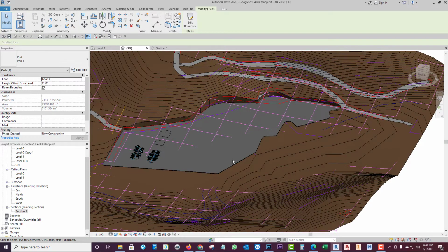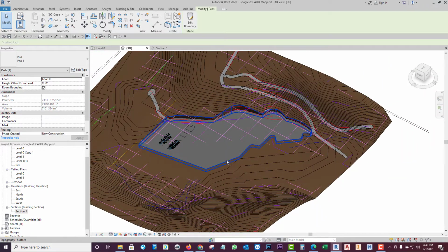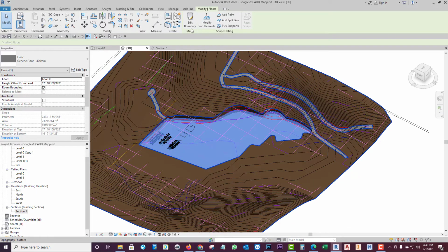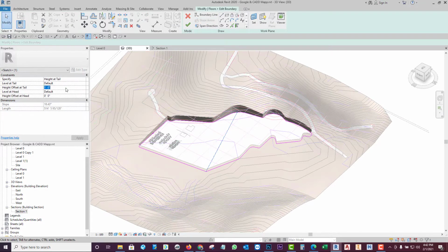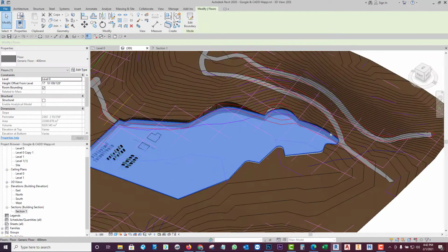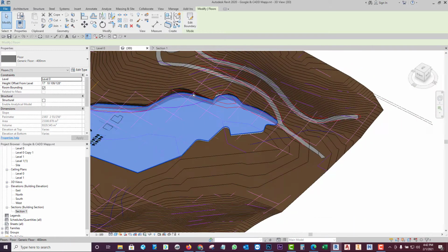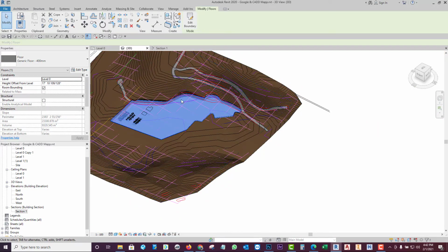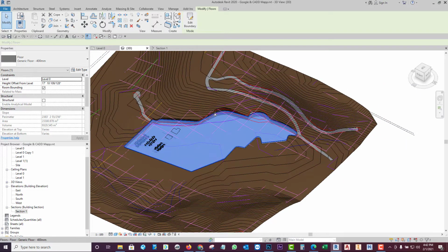So obviously the concrete is going to try to minimize the drop, so I'm going to put a slope on this slab from here to that edge. So I touch the slab, edit, and I put the slope, and I say from this corner to that corner. The height of the tail I'm not going to change, and the head I'm going to put 9 feet, apply. Probably is good enough. Obviously here is the more critical part, but right here is flush, so I'm going to leave it like that because we are not trying to be perfect on the slopes of the asphalt.